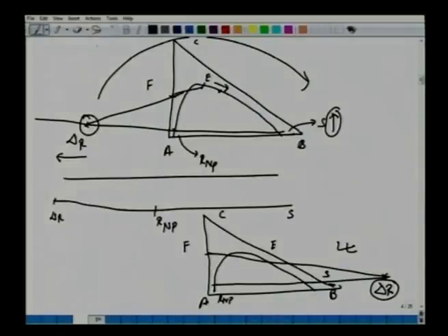All right. So before this, let's just try to summarize that we have been able to locate the locus of this del points as the amount of solvent is increased. So to start with, the feed composition is given to us, raffinate composition is given to us, and the solvent composition or the quality is fixed to us. We are only changing the amount of the solvent.